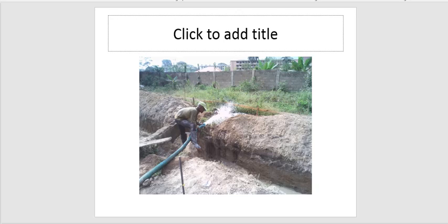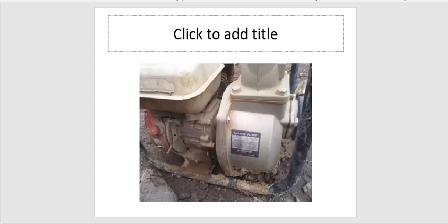So you see, it makes it a bit difficult to work in such an area dominated by this seepage activity. And of course, as I told you, it's not only that we are exposing seepage. If you're not careful, it weakens the soil strength. Now, can you imagine? This machine pumps 1,000 liters per minute. So you can imagine if you are doing that for close to 30 minutes, how much water we keep pumping in order to have the comfort of working.